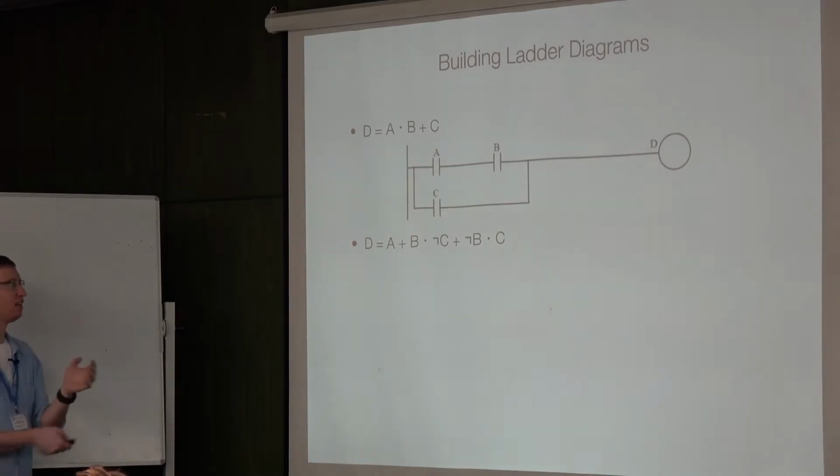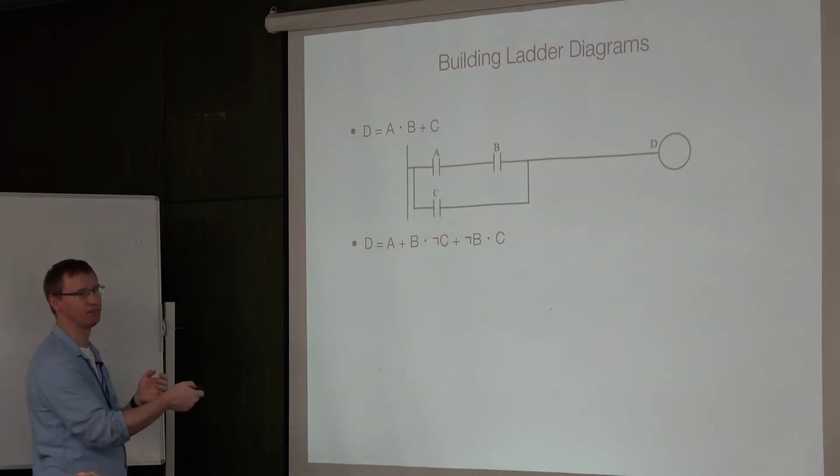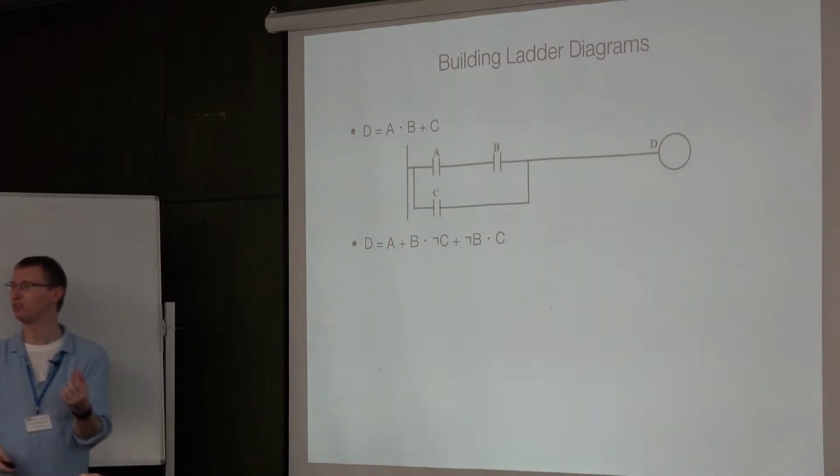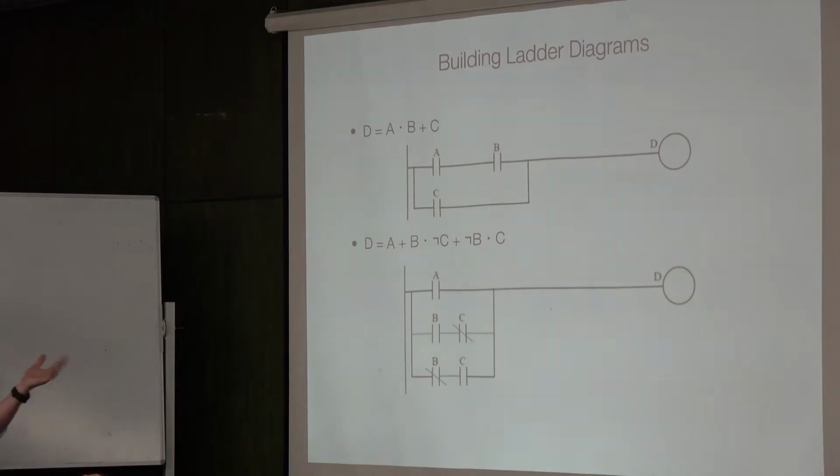We can take something more complex, where this symbol here denotes the negation. So this normally closed contact would just look like this. Then developing a control logic basically means translating these written Boolean statements into these ladder diagrams. That's what we do. First, we have to design those logic rules, but we also have to translate them into the PLC, and we can do that via these ladder diagrams.